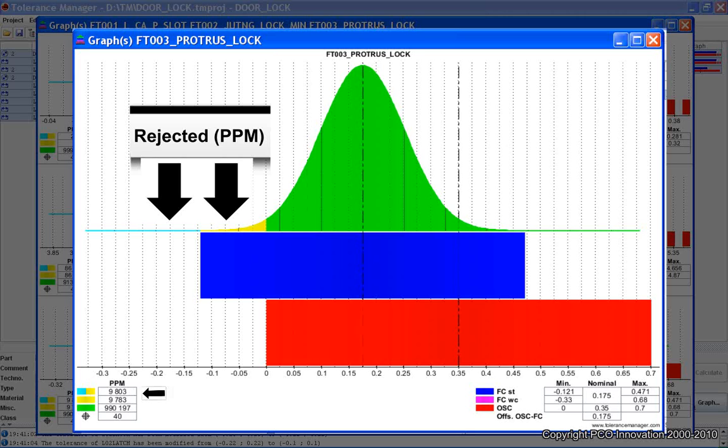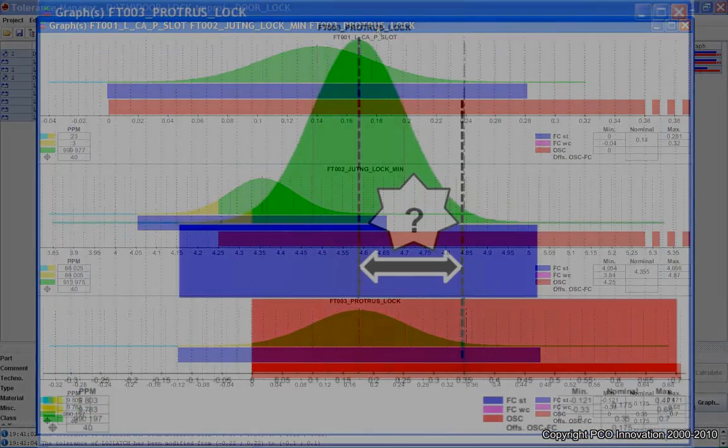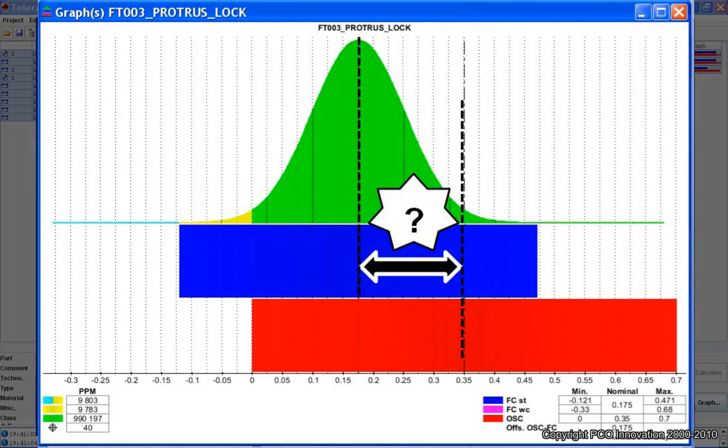We can see in our example that there is a gap between the range of the functioning conditions and the computed range. We will then have to recenter our condition to come back in the limits defined by the functional specifications. We have to move the nominal of one of our parameters to recenter the condition. We remind you that in a capable tolerancing, that's the range of our tolerance ranges which determines the dimension nominal values.